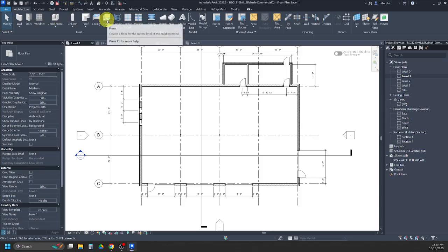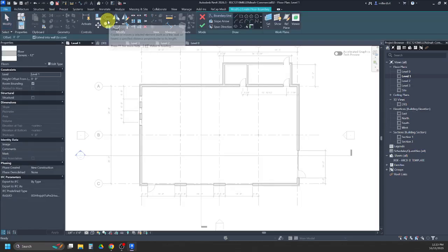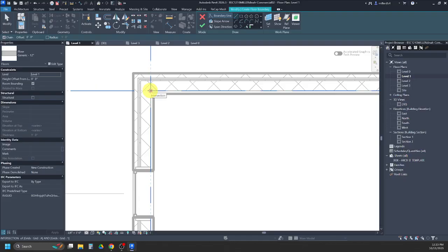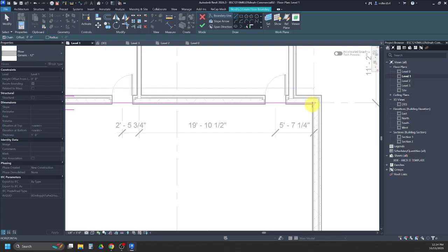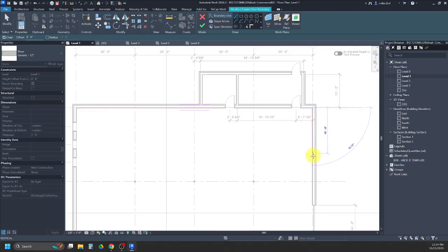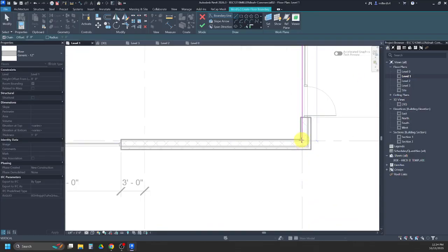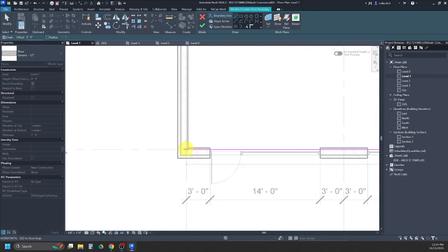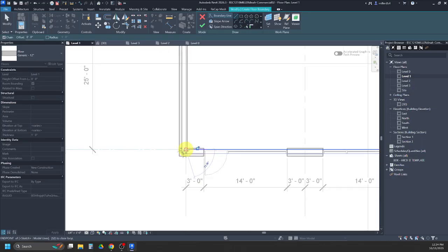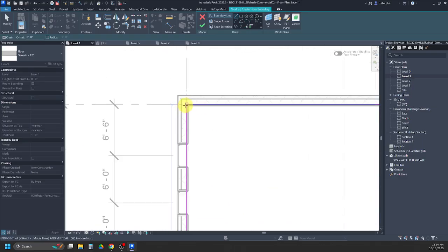Doesn't have a keyboard shortcut, but it's this button here. And you may remember when we go into floor, it kind of blocks everything out. And instead of using like pick walls, what I'm going to do instead is I'm just going to use the line tool to just draw a line from where A1 intersects all the way down to A5, down to my intersection at C5, back over, and then back up.